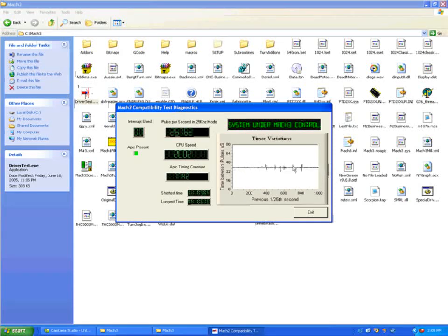These little jittery lines you see are slight variations, or microsecond jitter, in the pulse stream. This won't affect your motor typically. Those are very small variations, and this waveform is considered a very good one.